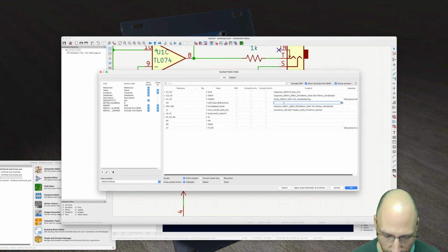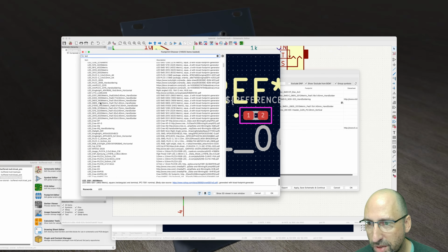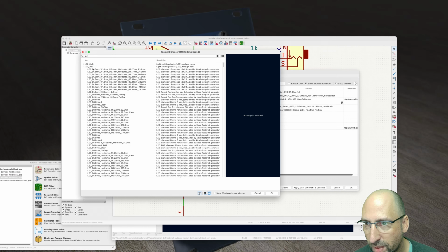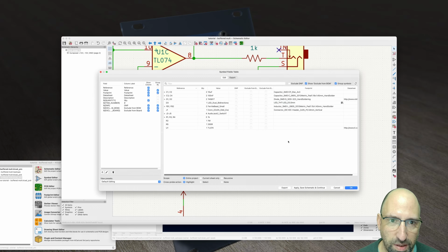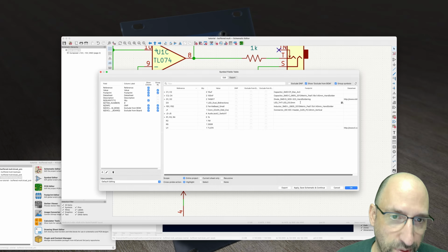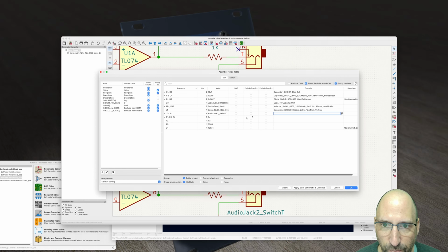So the LED, I know that it is, select your LED. I want a through-hole LED so that we can get it onto the panel, and it's going to be a 3mm package. Nice, with 2 pins. It's just a standard package. It's got a common cathode between the 2 LEDs inside the package, so it's only got 2 pins. So that's kind of cool. All right, so we've got an LED, 3mm LED.